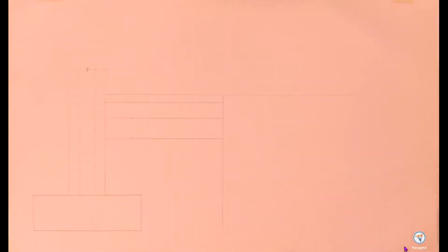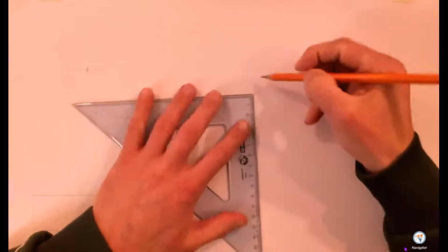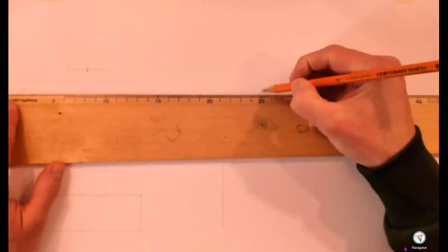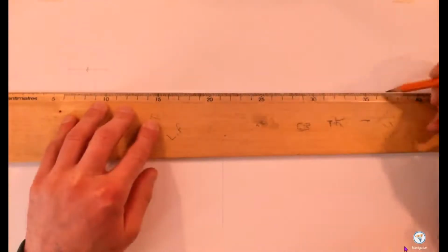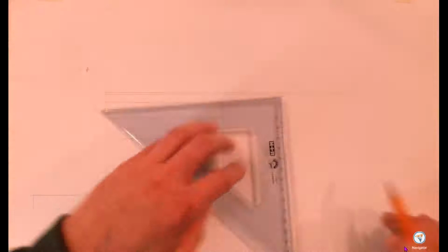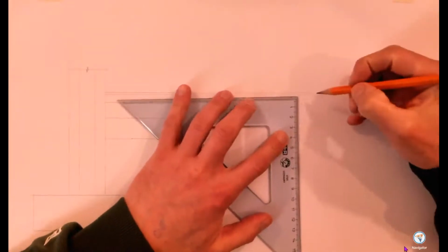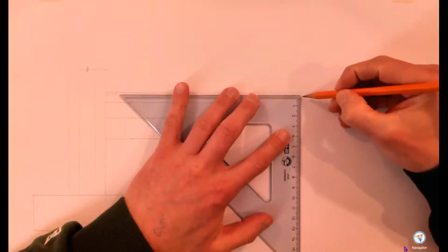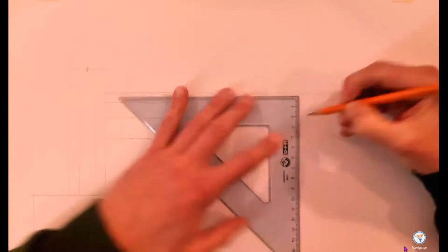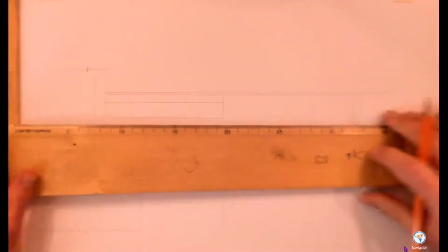We're going to work from the top down. I've got my finished floor level put in for the time being. It said there's a 20mm hardwood floor, so I'm going to measure up 2mm and put in my floor. There's my timber floor, the first thing I'm going to draw in. The reason we're starting from the top down is we want to match up both floor levels. We have our joist underneath, a 225 joist, so I'm going to come down 225mm, 22.5mm on the drawing, for our joists.